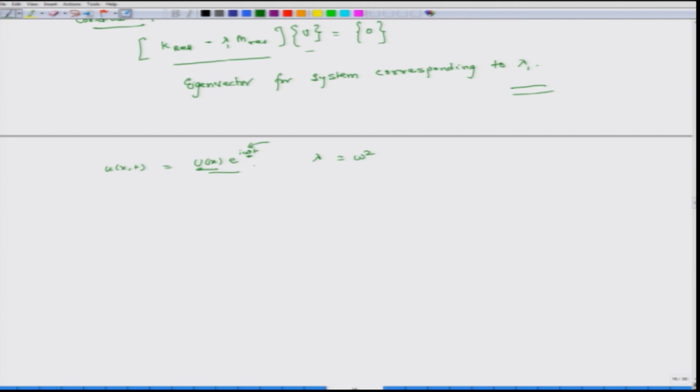Mode shape of the system means, so you have 4 nodes suppose, 2, 3, 4 and 5. First node does not move because why? Because it is fixed. So what does a mode shape mean? That when the system gets excited by first eigenfrequency, maybe U1 is like this, U3 is this and this. So this is your first mode shape, which means this is the shape or the boundaries between which the system is going to vibrate.